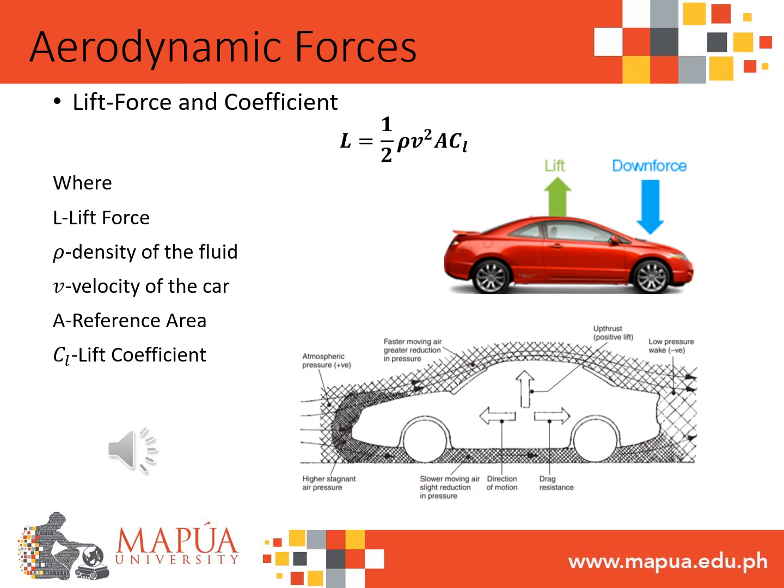As you can see in the figure, in a ground vehicle, lift force is generated due to the pressure difference in the front end and the rear end of the ground vehicle. The lift force depends on the density of the fluid, velocity, viscosity, and compressibility, and surface area of the object where the air flows over. The shape of the object and its inclination also influence the amount of lift force to be generated.